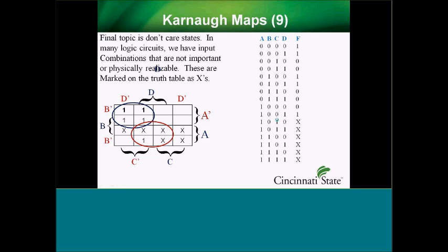We'll talk a little bit when we get into counters, towards the very end of the material. Sometimes if you're designing a counter system, which is kind of like a pseudo-random counter going in some prescribed sequence, like 0, 1, 6, 5, 3, 2, back to 0, maybe you have a state that it never goes to. If you include it, you can find out, from a design engineering standpoint, what the thing would do if it were to get locked into that state somehow.